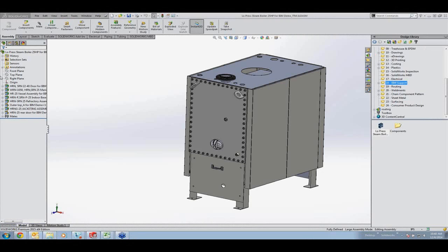There have been some changes to surfacing as well. In the past, we added the style spline. We still had the original spline, but now in 2015 we can turn a regular spline into a style spline by right-clicking on it and choosing Convert to Style Spline.